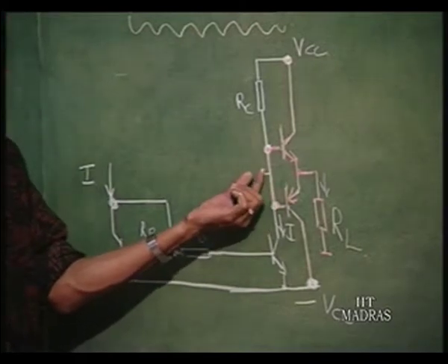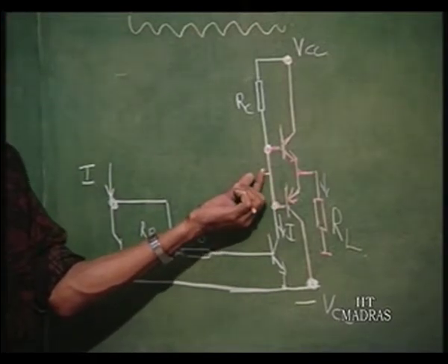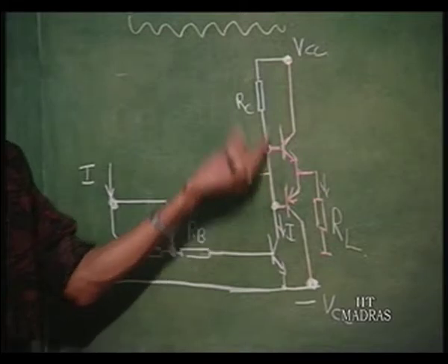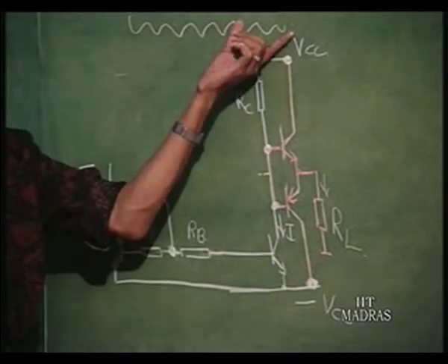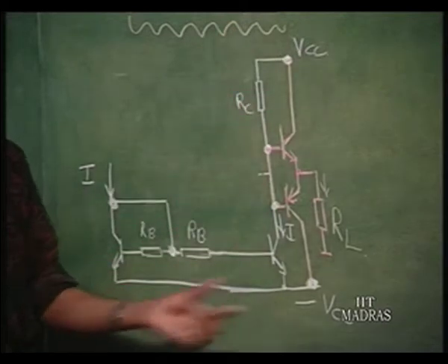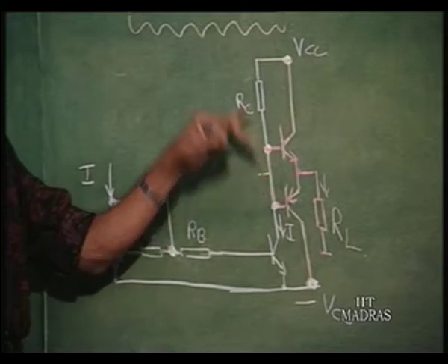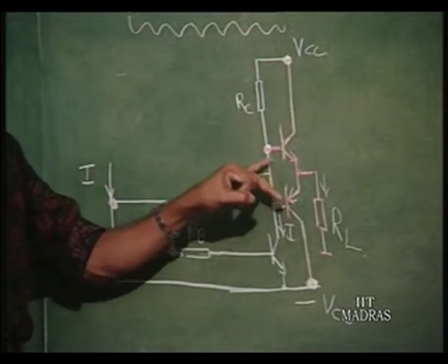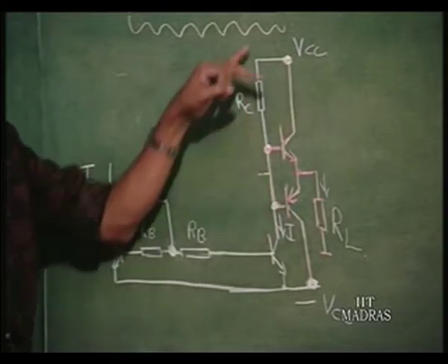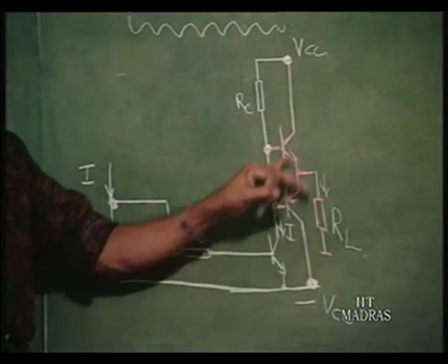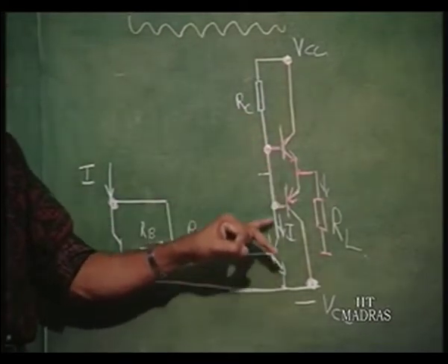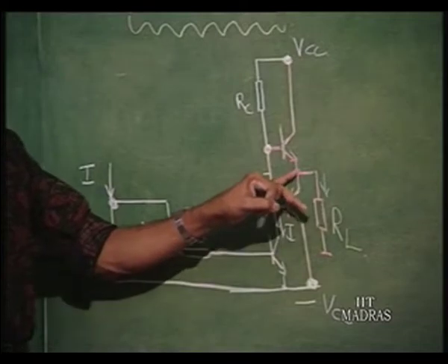So, the drive of the amplifier should go in terms of voltage almost up to VCC on this side and VCC on the other side. What it is capable of going is VCC minus V gamma for this, and minus VCC plus V gamma.